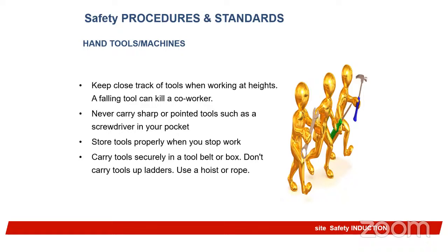So store tools properly when you stop work. Carry tools securely in a tools belt or bag. Don't carry tools up ladders. If you want to carry tools up, use the hoist. When you get to that height, then use the hoist to take it up properly. Use a hoist or rope. A simple rope can also do a wonderful job.